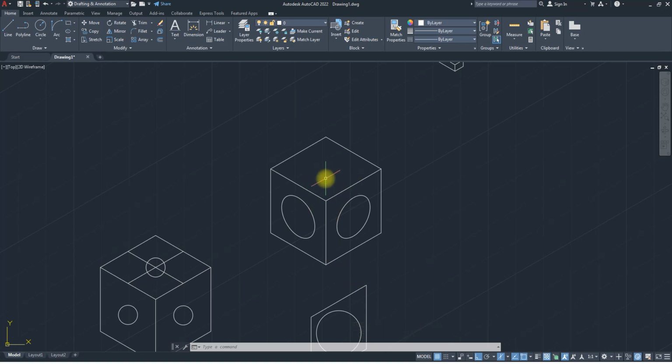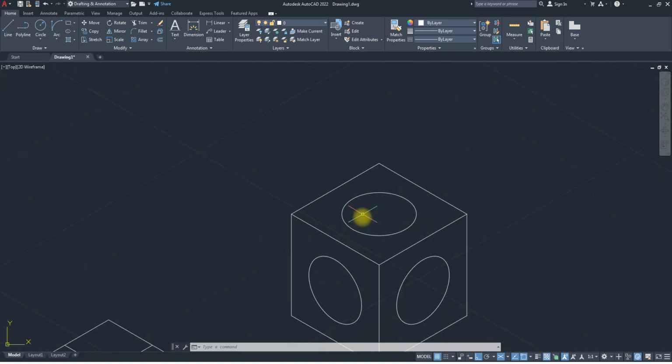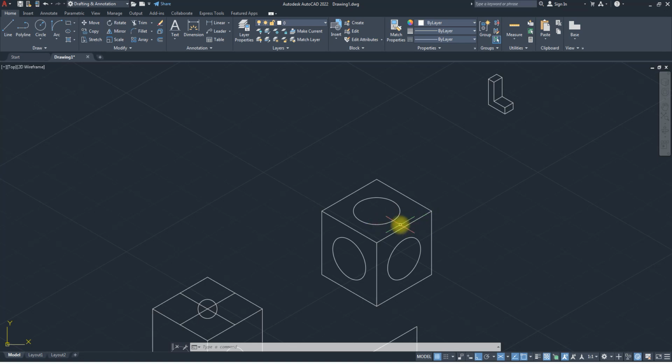Then we can also do for the top, ellipse, I for ISO. We have to switch our view to top view. Then go to midpoint, midpoint, wherever they meet, radius of 6. You can see that three of them look different and it feels like they are on those faces. Okay? So that's how you can use it.